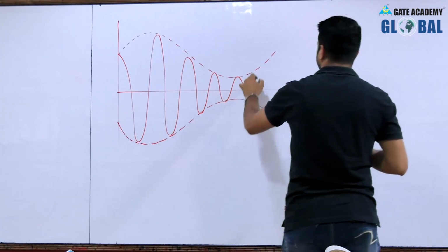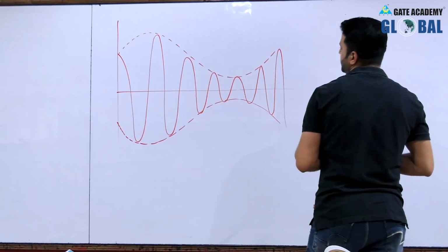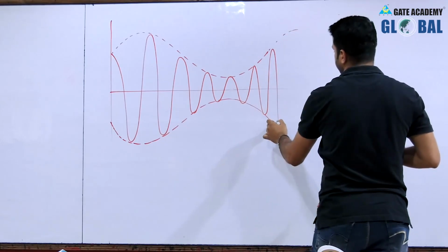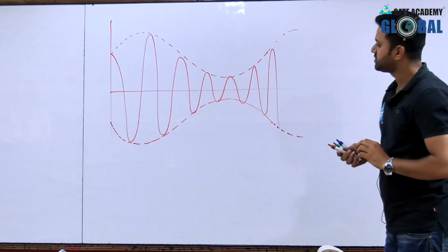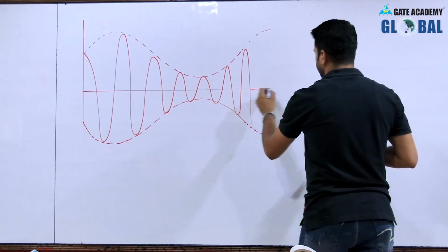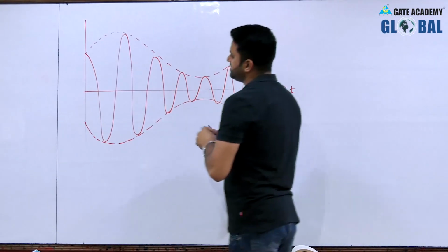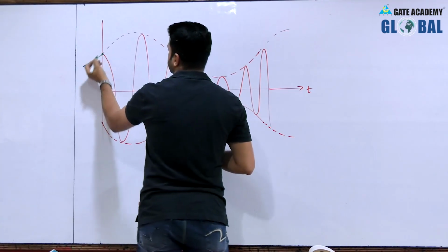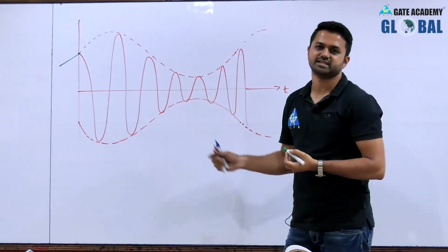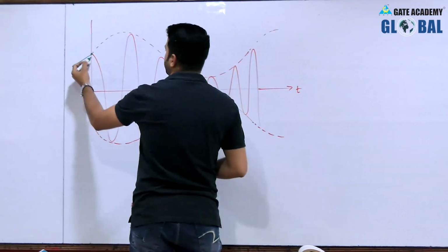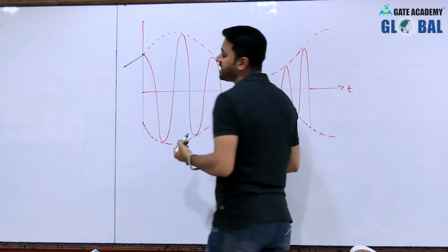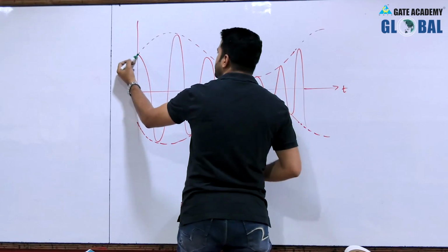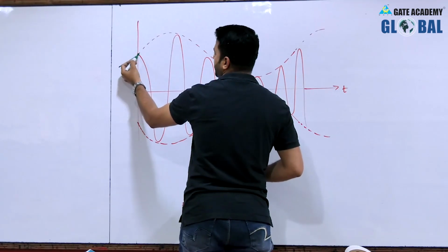We know this because we have seen the time domain waveform, and in the time domain waveform we know what the AM signal looks like when the modulation index is less than 1. So, this is the AM signal, and suppose the capacitor is charged to the maximum value. The green line is the capacitor voltage. After this, the input is the AM signal, and now the input is decreasing, while the capacitor is charged to the maximum value.